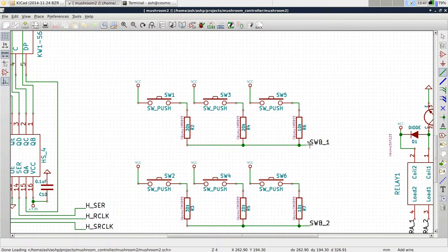So that means you can do your schematic in a way that the layout is easier to read, because you've not got crazy wires everywhere, with lots of crossing over and all kinds of crazy things when you put that on a PCB. You don't want that in your schematic, because the schematic you're supposed to be able to read.